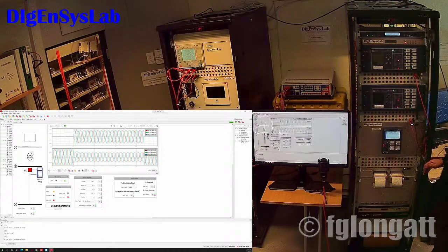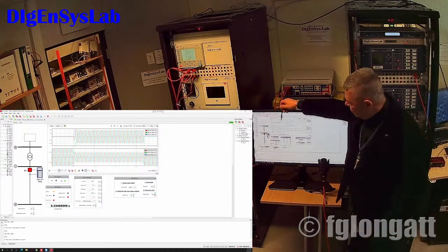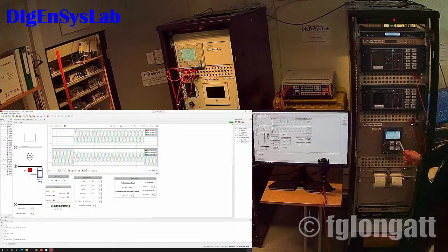What you did was sending this huge current into the relay, and the relay detected a fault, and it was a 50. That is a fault for overcurrent, and it's tripping, okay? And you can see over here, the relay is tripped, instantaneous overcurrent, and you can see right now that the breaker is open.